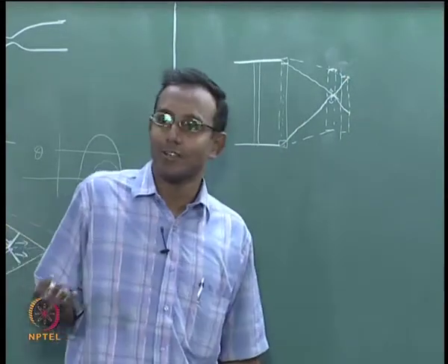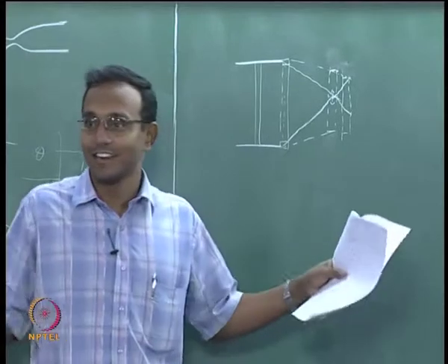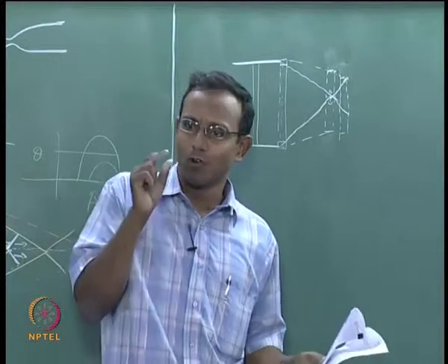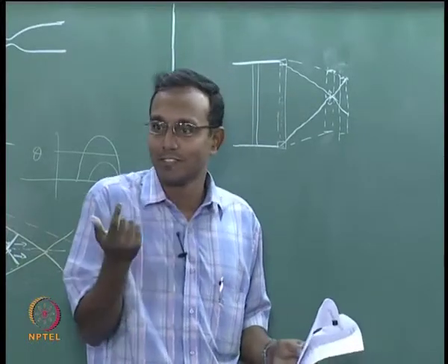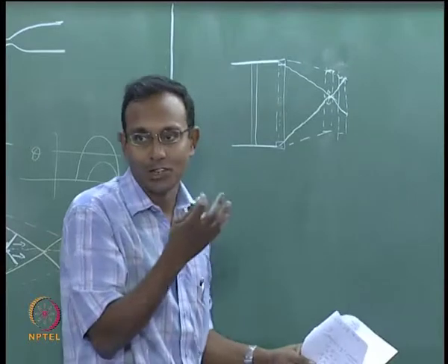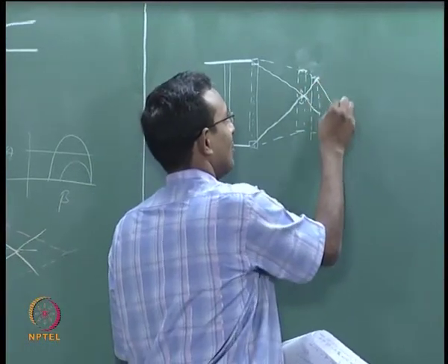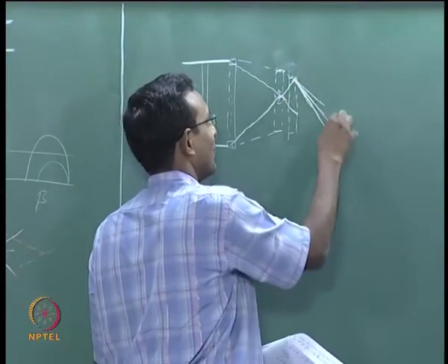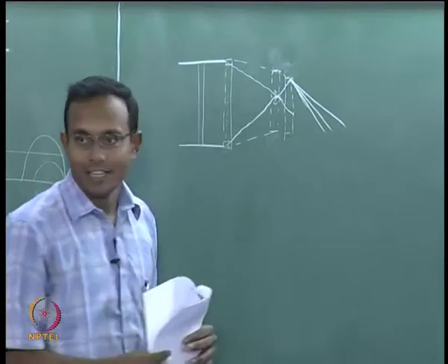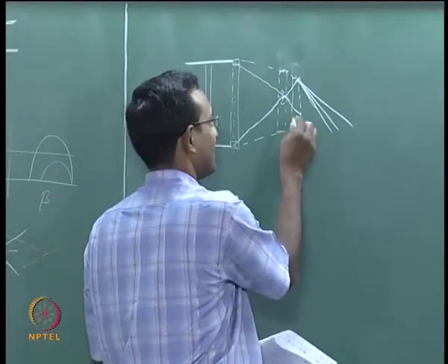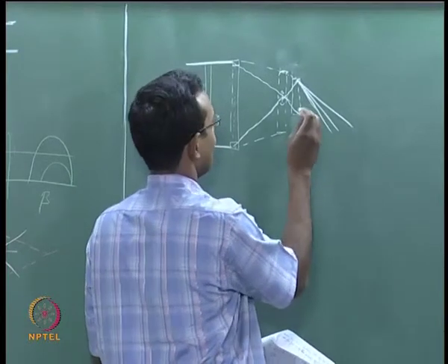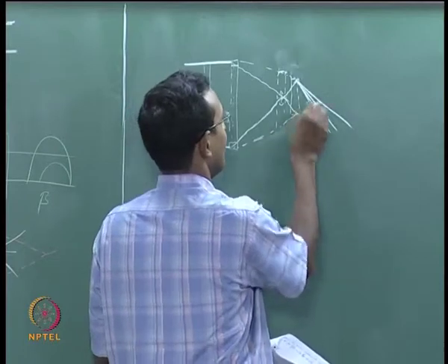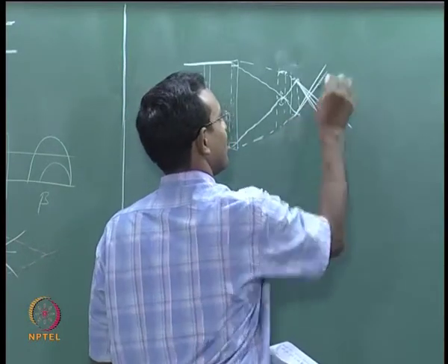Now what will that messenger do? He has to run, he will again start running, right. He is going to say decrease pressure by so much, and typically it is done by a whole bunch of expansion waves, and they do not go all together, they are like a shock, they go each individually. So there will be a whole set of fan of expansion waves running out. They are going to run this way, and similarly the same thing is happening on the other end. And they will also send out an expansion wave fan like this.